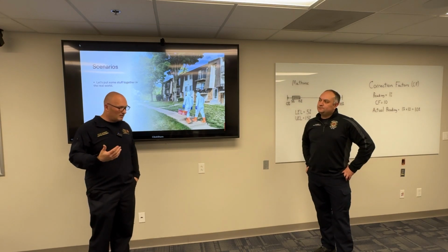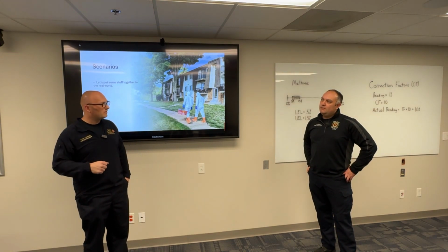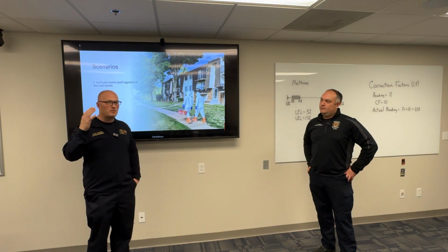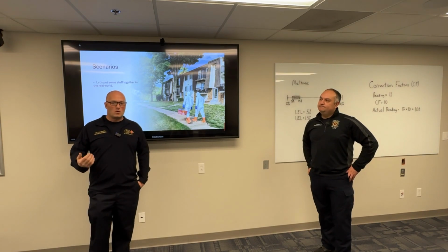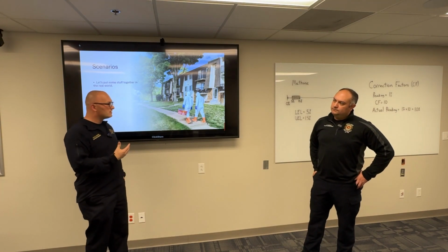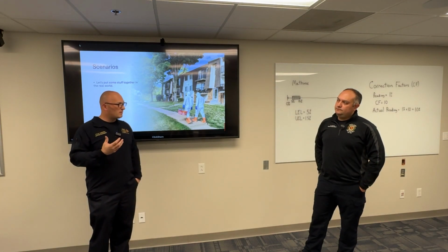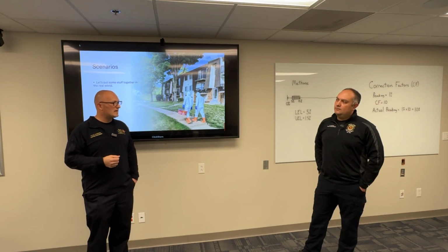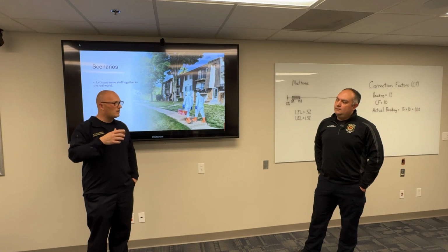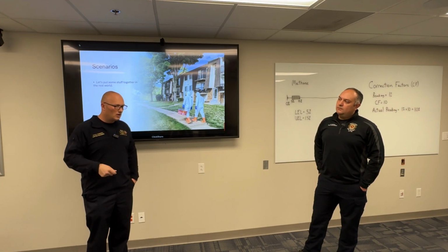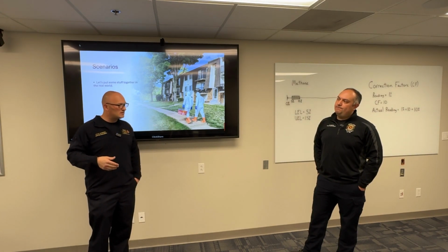So I immediately start thinking, hey, HVAC system. If it's equal throughout the entire house, there's something pumping it through the entire house. So we walk in the door with our meters and start getting some VOC readings, nothing huge. But you can smell it, a pretty strong, nasty odor, and as we travel the house, it's equal throughout. So we go down and shut off the HVAC system, and it's a finished basement.